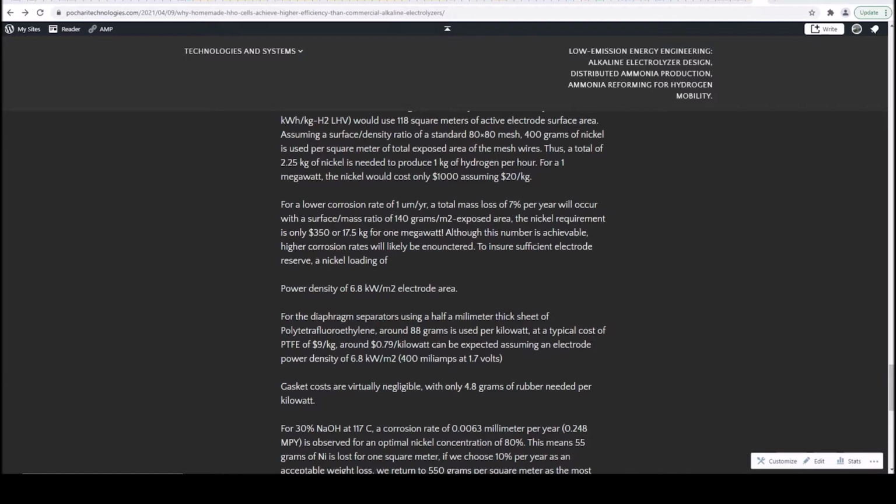Although again, as we said, the surface area is in a way irrelevant because it just directly relates to your corrosion rates. You could have a super high surface area mesh, but it means your corrosion rate would be so high that it wouldn't be viable. So, assuming you use a mesh, about 50% of the cost is material, and the rest is actually fabricating the woven wire, which they just take a weaving machine and they take really fine wires and weave them.